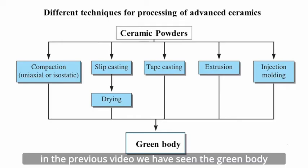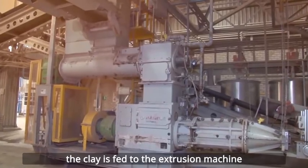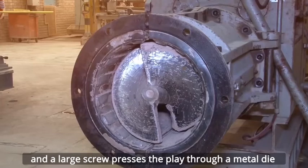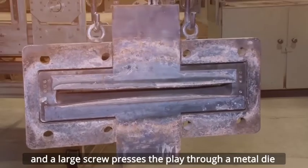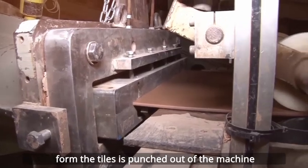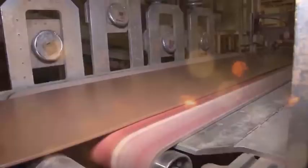Extrusion. In the previous video, we have seen the green body of tile is formed by extrusion techniques. The clay is fed to the extrusion machine. Inside the machine, the vacuum removes all air from the clay mix, and a large screw presses the clay through a metal die, and a sheet of material that will form the tiles is punched out of the machine. This process is known as extrusion.